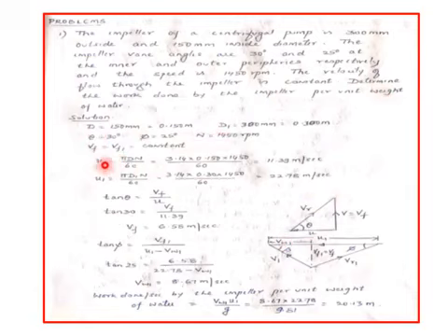Now using the velocity triangles that we had already discussed, since D is given and N is given, you can find tangential velocity U equal to pi D N by 60, which is 3.14 into 0.15 into 1450 divided by 60, which comes to 11.39 meter per second. Similarly, knowing D1, you can find U1, which comes to 22.78 meter per second.